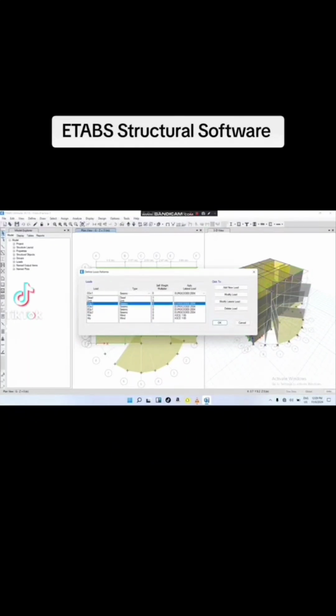We need 4 types of earthquake in the 4 directions: X1, X2, and then Y1, Y2, and then we have wind in the X direction and wind in the Y direction. Plus the dead load and the live load.